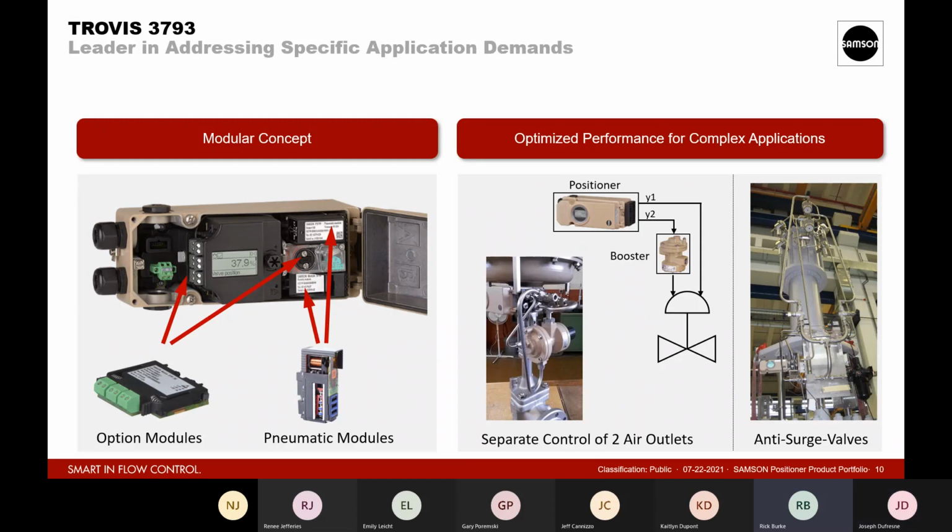One application we did was some large 10, 12-inch double offset Teflon line butterfly valves on a membrane system with chlorine. And we were able to control these huge butterfly valves to plus or minus 0.25% accuracy with 3.5-second stroke times, which is really unusual. The resolution of these positioners is phenomenal, and the people that saw it in the field that had never seen it said it was amazing. So it's an awesome advantage for us on some of these applications.